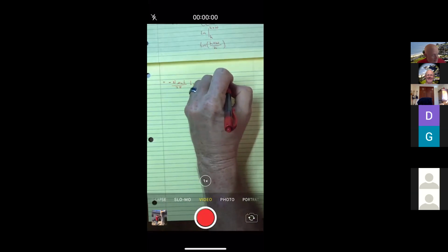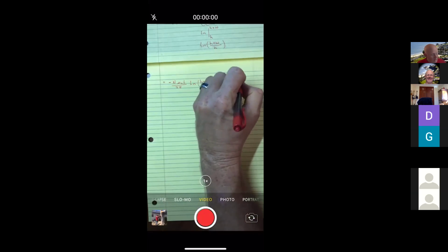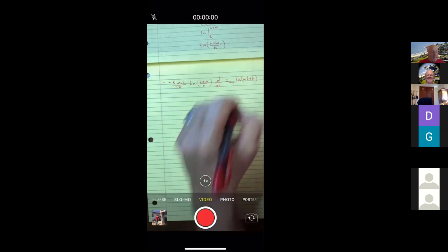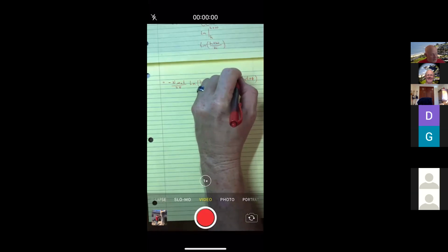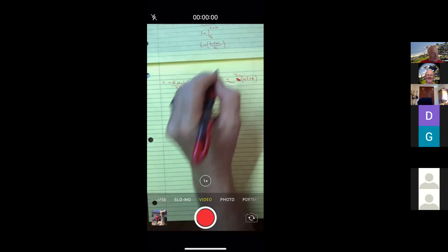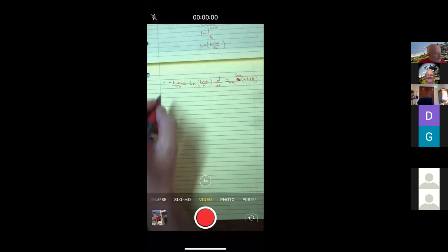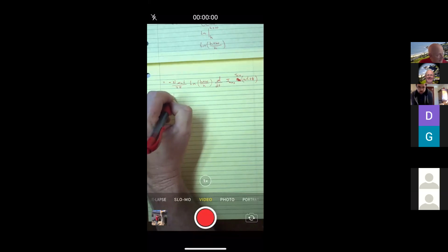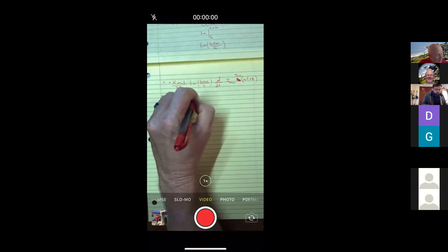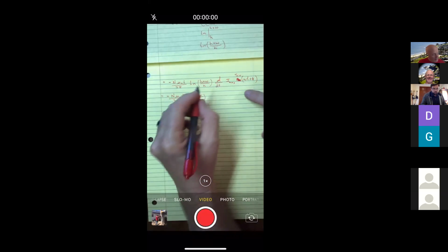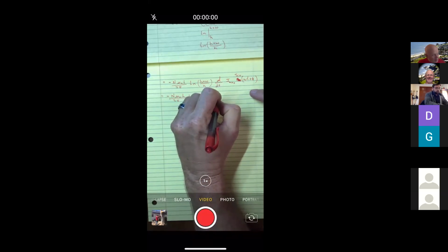And so maybe I'll write out the equation for the current. Oh, sorry. The equation was a sine. I'm already thinking derivative. Okay, so that's the equation for the current. And so when I take its derivative, so minus n mu naught L over 2 pi natural log of (H plus W) over H. And then the time derivative, well, the maximum current is a constant.